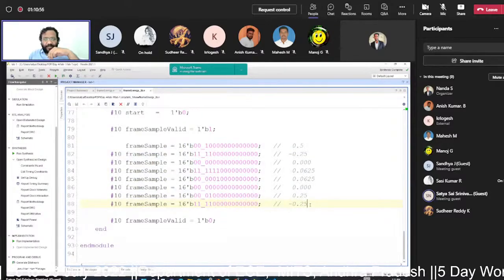It's not modular in structure, and at the same time it is also difficult to write sample by sample in this fashion. So earlier I told you we will be using file IO operations, wherein we take the data from a text file, load it into the test bench, and read sample by sample from that file, give it to the module, test the module, and the outputs we are getting from the module, we will dump into another text file.